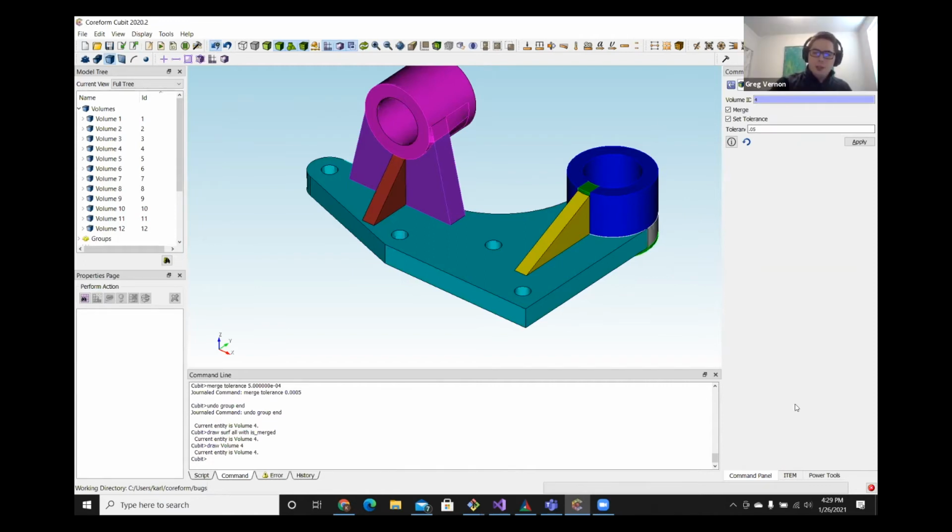And it is a good point. There was a Q&A that I answered too, but when we do webcuts, unlike other software that do partitions, when we do a webcut, it completely disconnects volumes from each other. So they no longer communicate. If you were to mesh each one of them individually, their mesh edges or mesh nodes wouldn't communicate to create a conforming mesh.